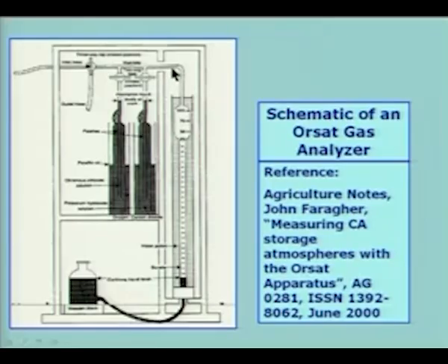So, even if moisture is present in the incoming gas sample which we are going to measure, the water concentration is not going to affect the measurement, and therefore, we call the measurement dry basis.